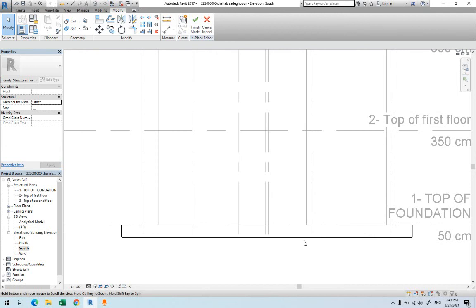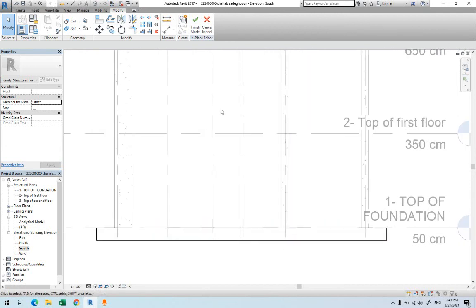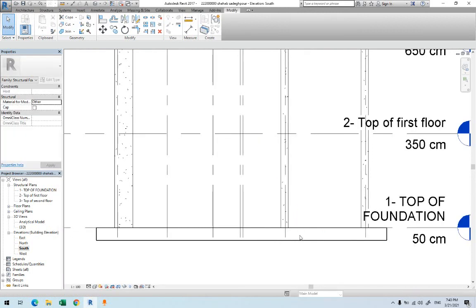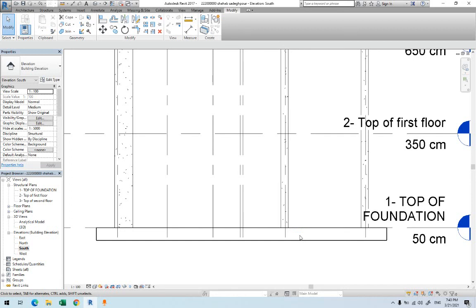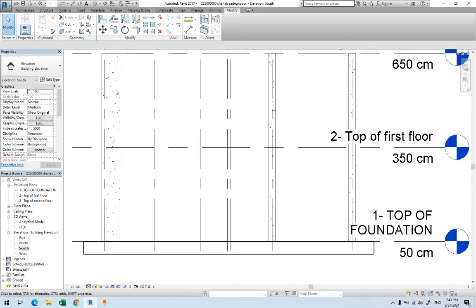So you can simply edit the extrusion before finishing it. If you finish the model, that's basically you're done with the foundation. After finishing, you click on finish model, then the extrusion, because there were two things: we came into the model, then we went into the extrusion. Now we have the foundation as it is.